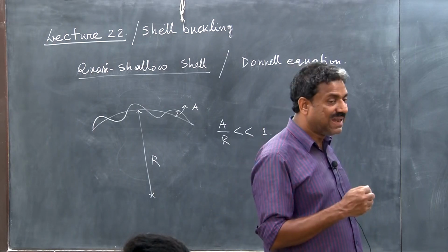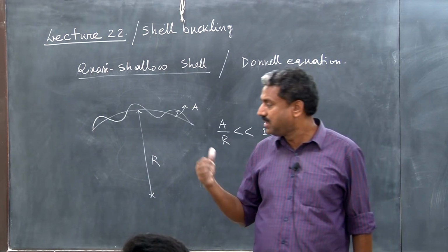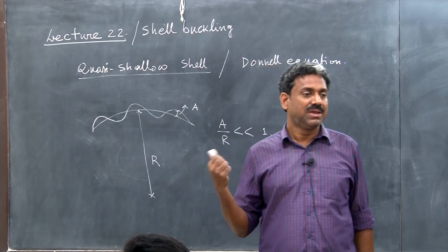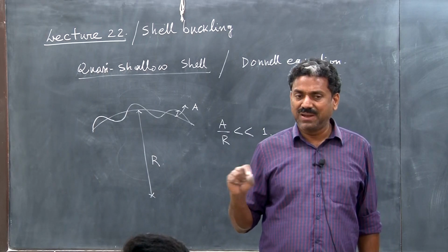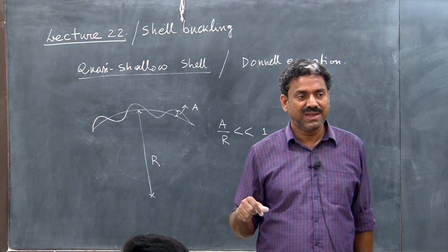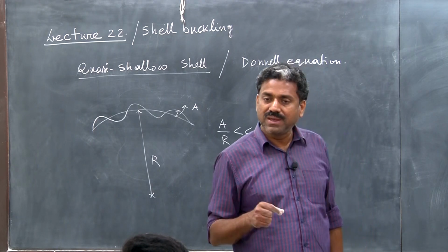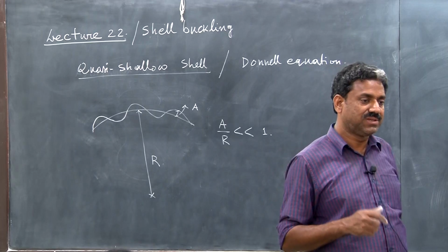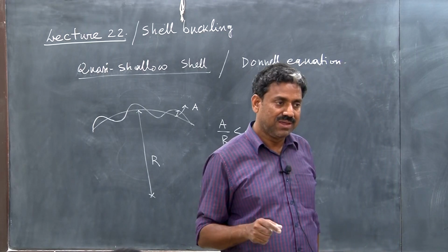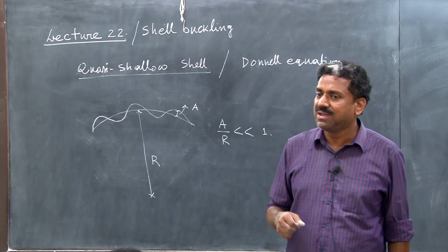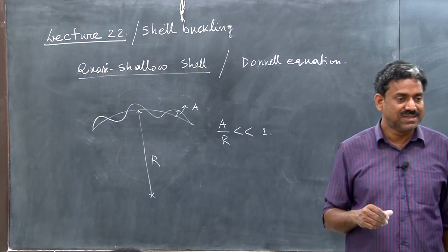But unlike a plate, because of the curvature, in a shell the in-plane forces and the out-of-plane bending are coupled essentially. So from the very beginning, we have to consider the equilibrium of the in-plane forces as well. That's a difference between plate theory and shell theory.